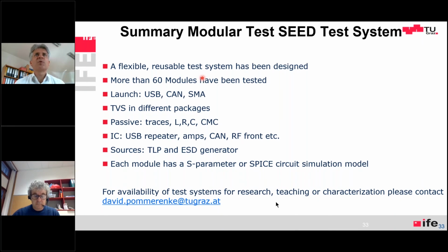then you should be able to reconstruct your LTSpice model. One thing I added here as the answer is that for the switch itself, one should set the R off of the switch to a very high value, like 1 giga ohm. I think the natural setting in LTSpice is 1 mega ohm for R off. That's too low. So that's the only thing which has to be changed from the native LTSpice model, I think.